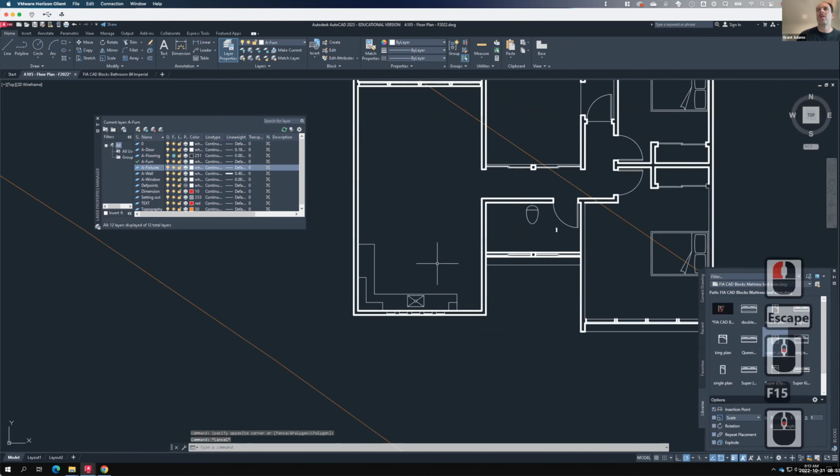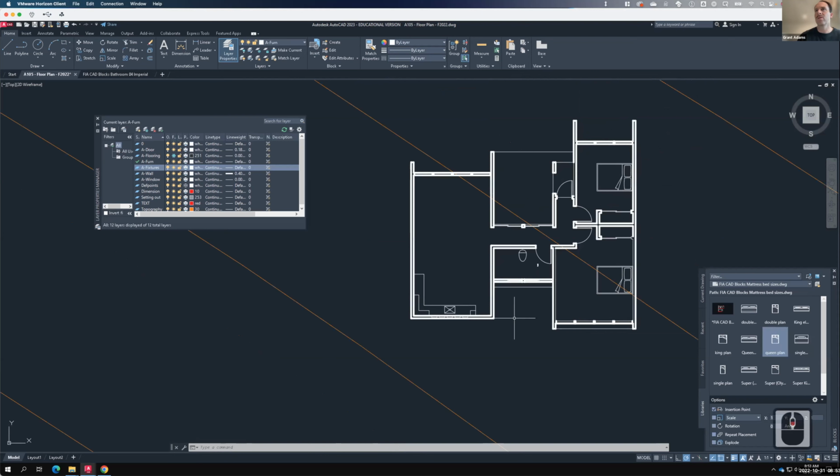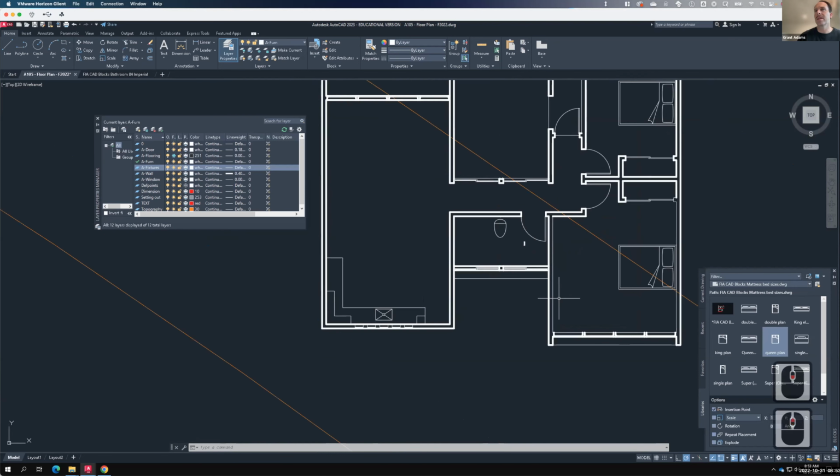So I have a few other little overhangs that would need that hidden two. This line, for example, would need hidden two, and I could manually go in and make those adjustments. Looks like there's a few lines that I'm missing here that don't have the thickness. Like this line obviously is part of the walls layer and it never got changed. So let's go ahead and change that. Oh, it is on the A-wall. I wonder why it's not showing as thickness.